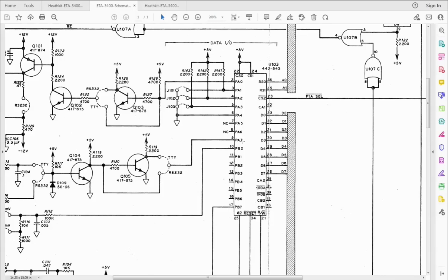I think the way it does it, I briefly looked at the code, but it sits there, and as long as this is a stop bit, I think it's a low logic level, it thinks that the line is idle. The minute a start bit is generated, this line jumps high, and it is assumed that a bit stream for a byte is going to come in.